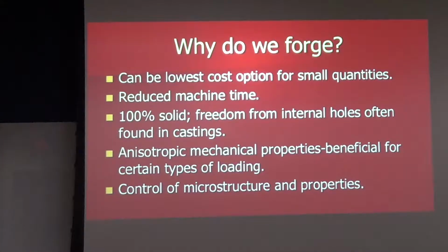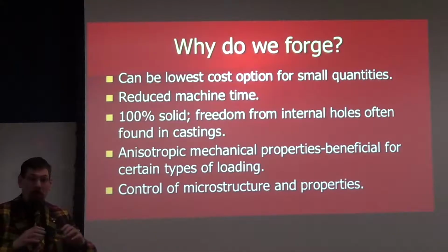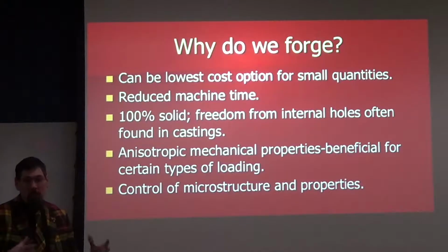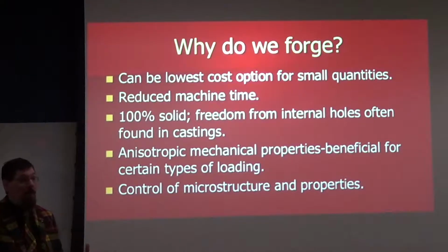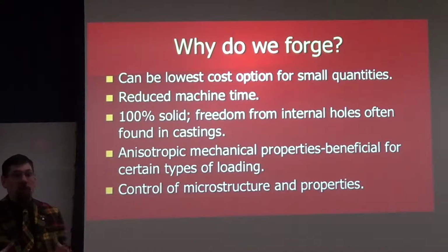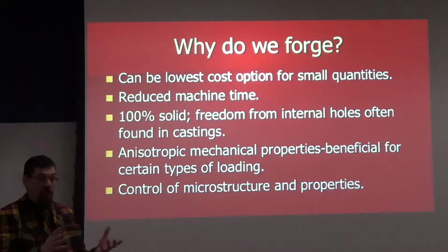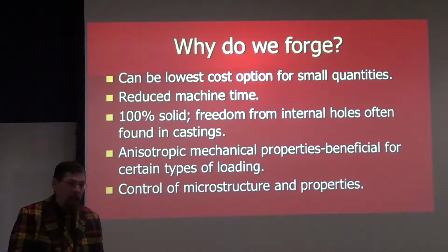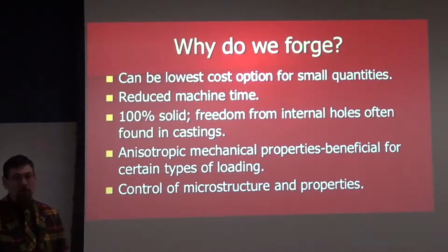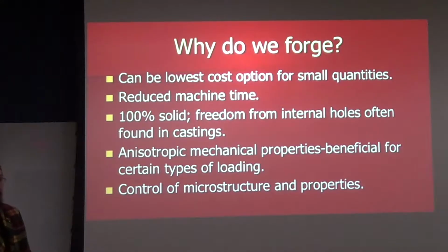Another very important thing is that if I were to compare the amount of time to machine a part, if I take just a block or a big bar and I want to machine a shape out of it, I can do that. We have the technology, we have big machine tools, small machine tools. We may even be able to do that somewhat quickly, but we're not going to be able to do it as fast as we would be able to take something that's already, say, 80% of what you need is already there in shape before it gets to the machine tool. So you have reduced machine time.